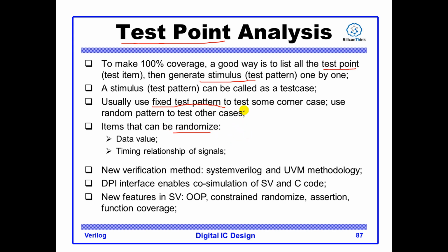The fixed test pattern is used to test some corner cases, such as if you want to test the function of an 8-bit A sub B. So the combination of 0, 255, 0, 255, maybe call it a corner case. Yes.